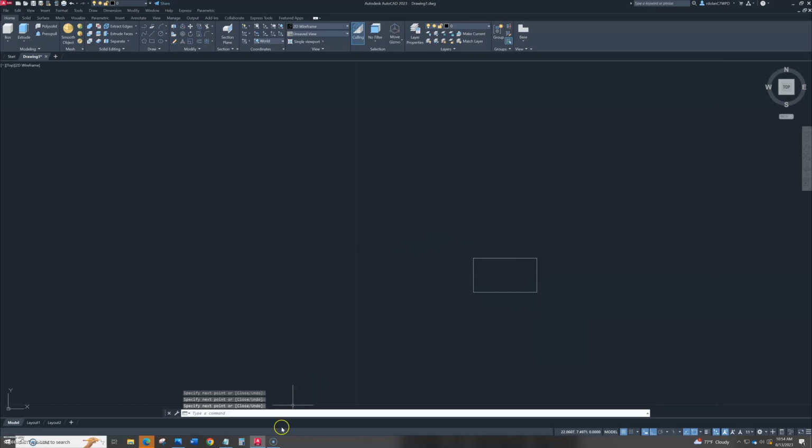All right, now I'm going to put the center part, and that is 0.190. And actually, before I do that, I'm going to offset this. From here to the center of that hole is 1.75. I'm going to offset that in this direction.